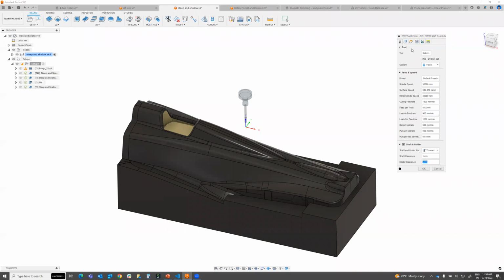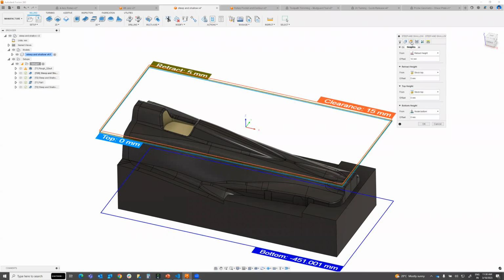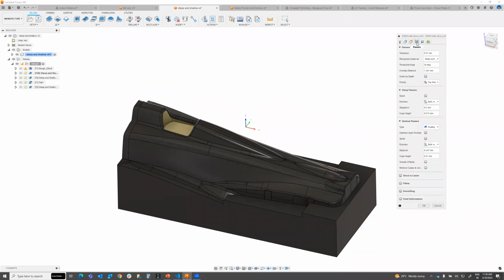Once you set this and go to the options as it is, you can set the pool area machining and where you want to machine. Here the important thing is whether you want to do both direction cutting or single direction, and also whether you want to use parallel passes, called raster or scale up. If you use the parallel, you will take raster passes. Then the balance will take into 3D offset. And also you can set the first priority, whether you want to do the top first or the steep first. The top will be done first, then you go to the steep areas.